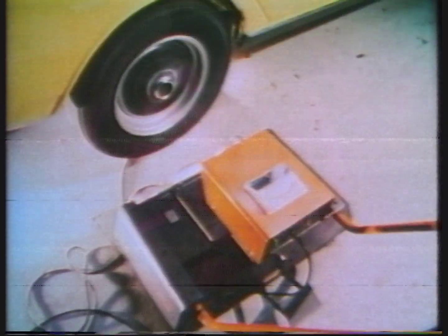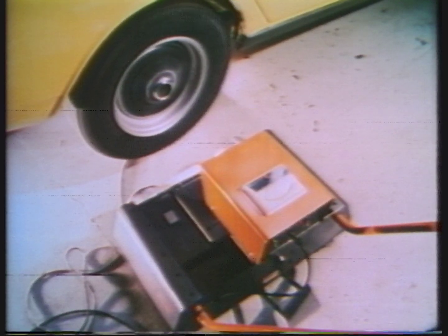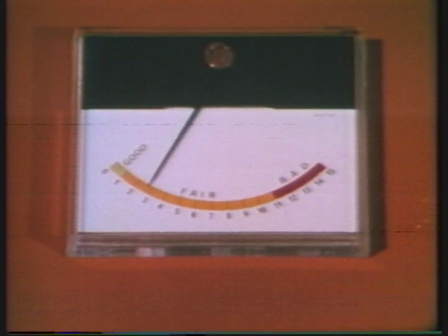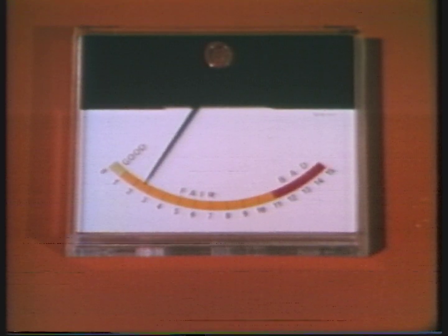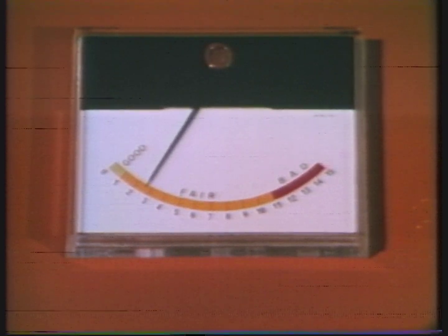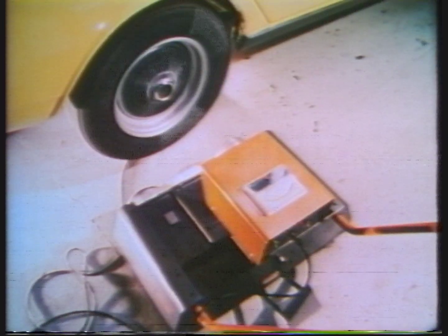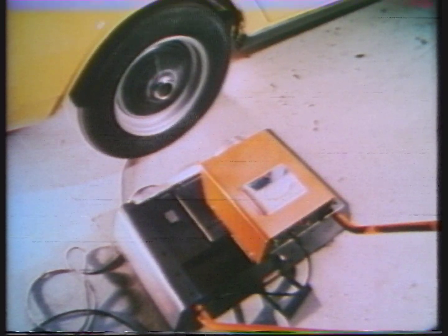The operator at the wheel balancer must instruct the assistant regarding speed and take his reading as soon as the pointer steadies. The duration of running must be kept to a minimum to protect the differential gears. 30 seconds for spin, maximum of 3 spins per wheel.